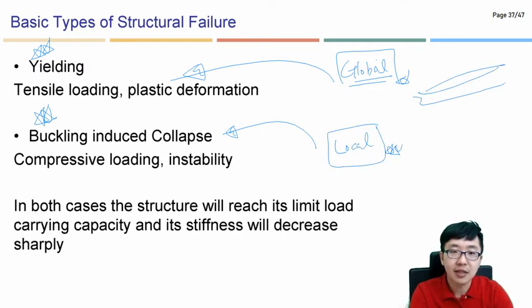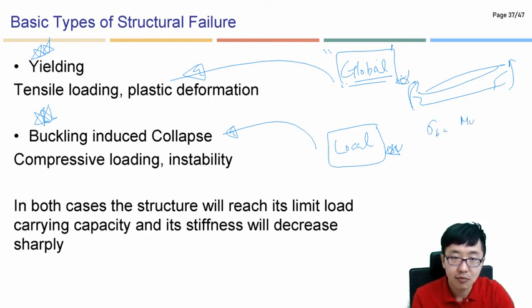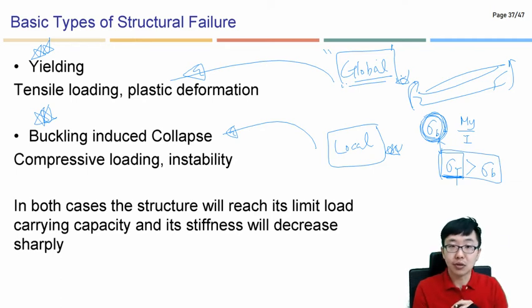Once we apply the vertical bending moment to our structures by global structural analysis, we can assess the safety of the hull girder, which means that bending moment M y over I, so that we can get bending stress values, and then these values will be compared with the material properties like yield stress. Of course, the yield stress should be greater than the bending stress, right? So that we can think that, in the global perspective, our structure will be safe.